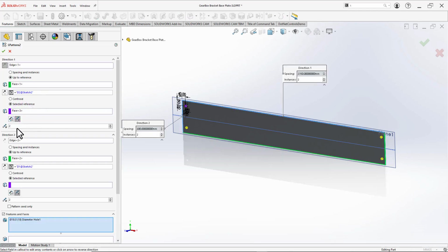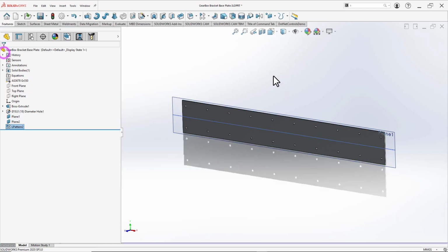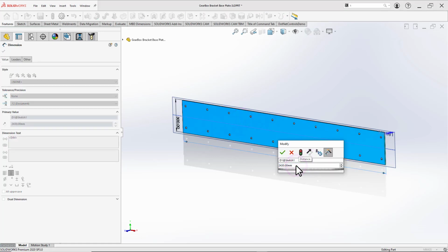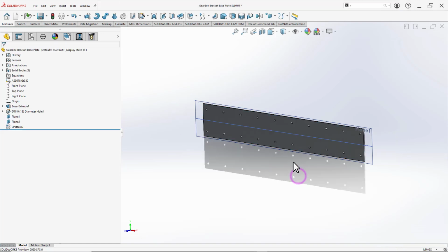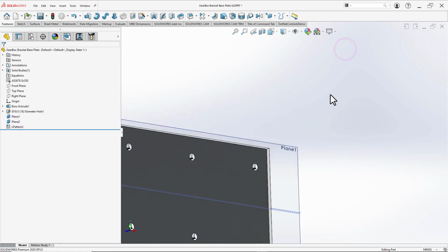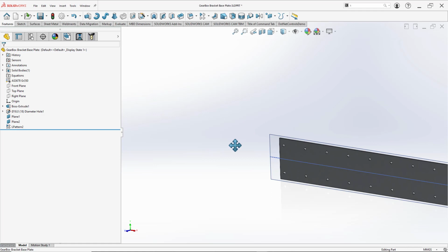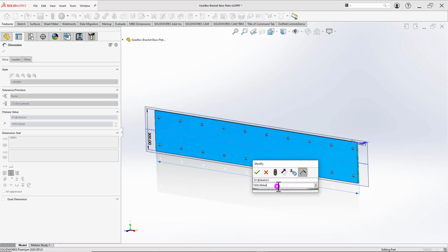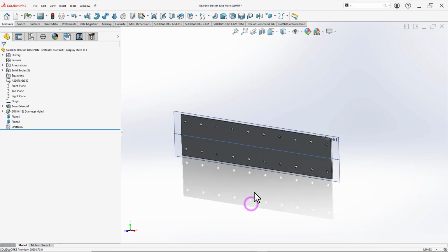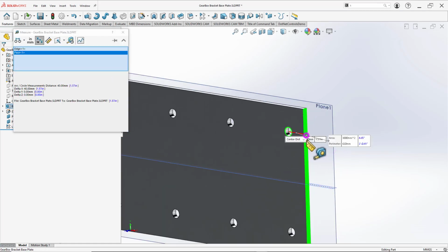Another really amazing thing is, if I told SOLIDWORKS that I want the number of these holes to be 10 instead of 2, once I change the size, I'm certain that I always have the quantity that I entered here. I can also define an offset, and the offset from these two faces is always the same regardless of the size of the plate itself. If I go even smaller than that, the quantity of the holes is the same, only the spacing shrinks a bit so that I get the offset that I defined inside that feature.